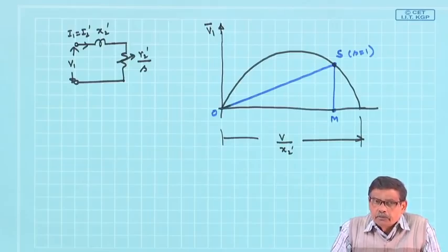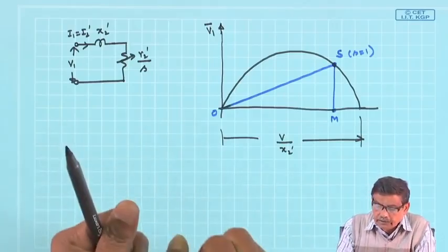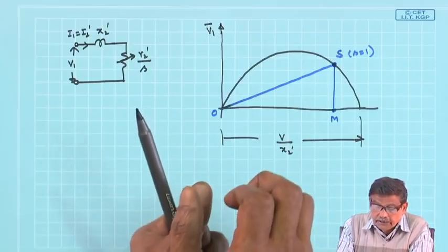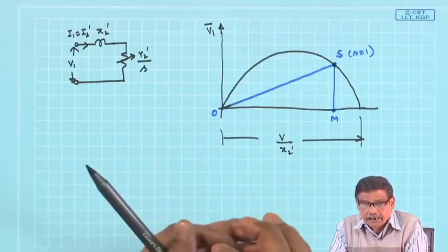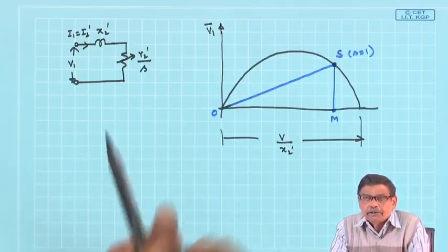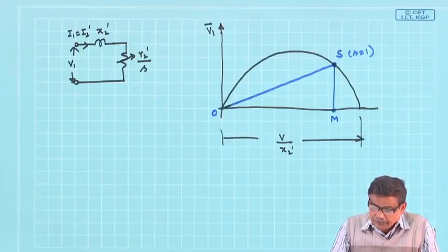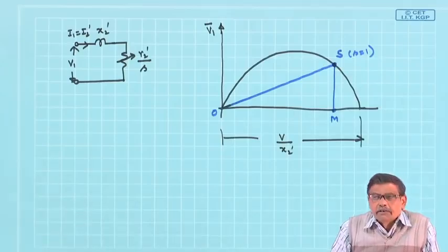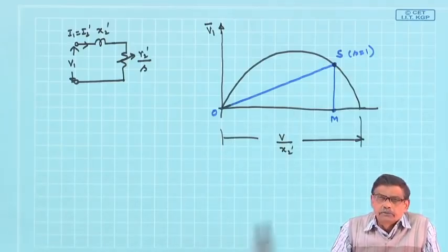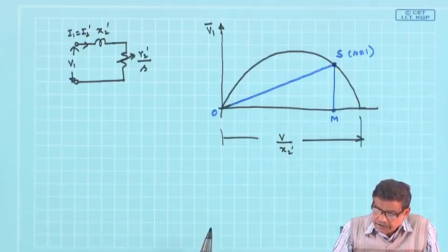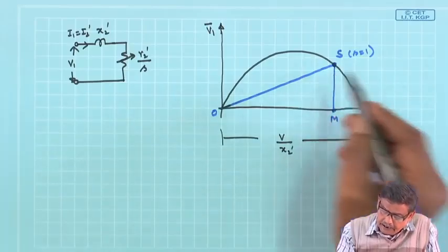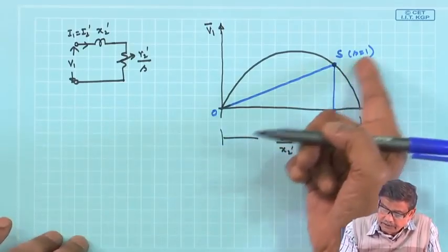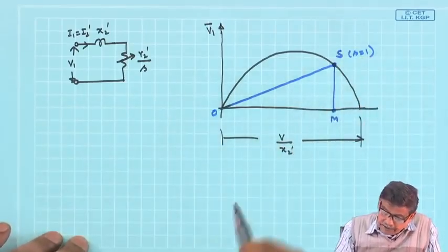If someone wants to hold the rotor with applied voltage, he will feel the punch of that. It is trying to rotate, you are obstructing that. That is true, it has developed torque, but you are not allowing it to run. Therefore, no question of any output mechanical power comes in, and N R equal to 0, that is why slip is equal to 1.